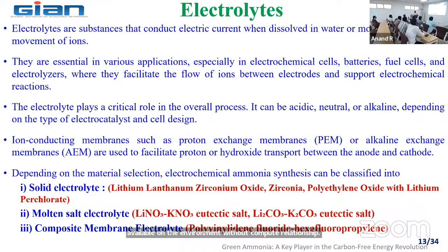So for material selection, the selection of catalyst, you need to go through different catalysis studies, like finding the operating temperature. For doing so, you need to do TGA, thermogravimetric analysis, to find the optimum operating temperature at which the catalyst behaves well. Because ultimately, if you add 1 kg of catalyst into the reactor, it should not burn. After several years of trial, I don't want the catalyst to be underutilized.